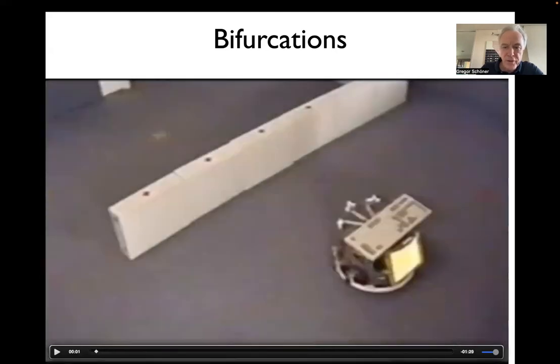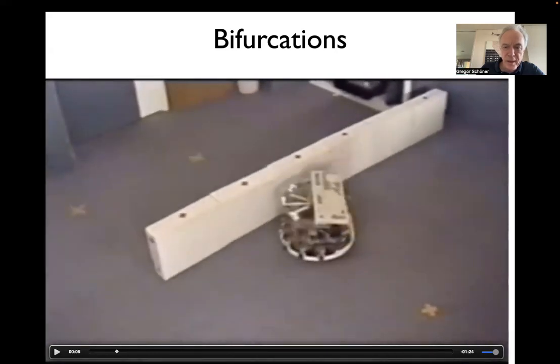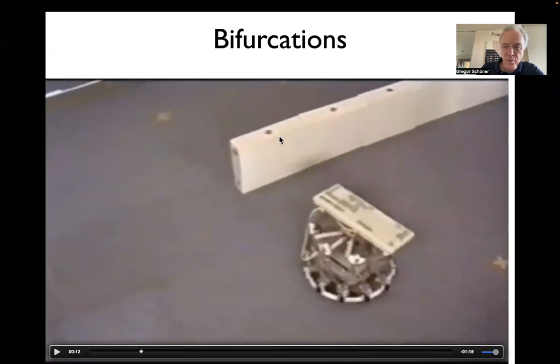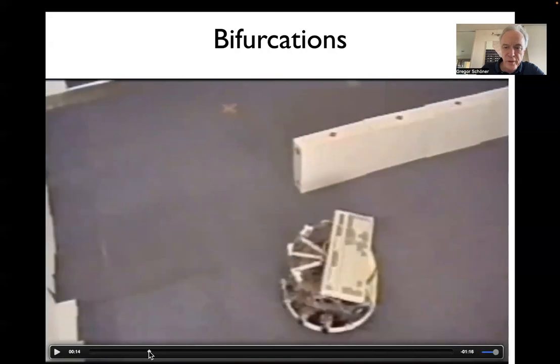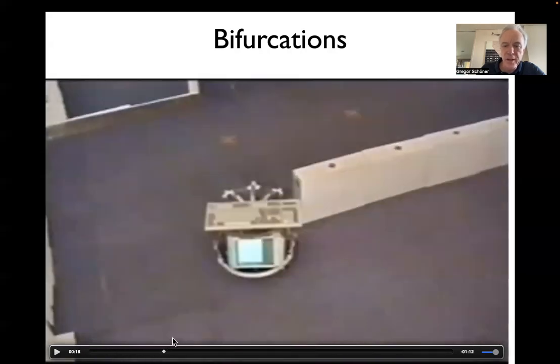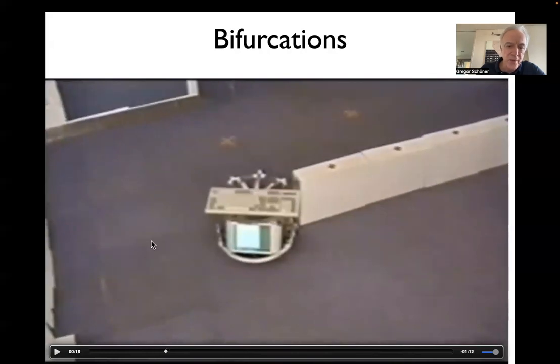The other thing I want to point out in this simulation is that it's only a local approach, right? This approach tells the robot, now you can't go this direction, and it goes away. And as it goes away, the influence of these obstacles goes away. So now behind the robot, it doesn't even notice that, and even after turning, doesn't have a strong influence because the distance is large. The robot doesn't really have a global plan, so it is attracted back to the obstacle really just in terms of angle, right? It can turn now because the obstacle has a smaller influence, and then it only knows the direction to the target, doesn't know that there's an opening here.